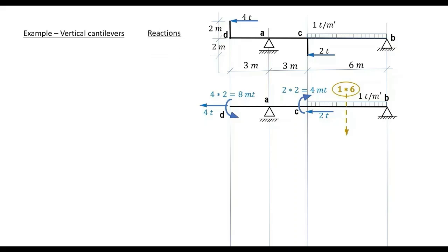We determine our reactions. We have one reaction YA at A and 2 reactions Y and X at B, as B is a hinge. Our first equation of equilibrium will be moments about B equals 0.